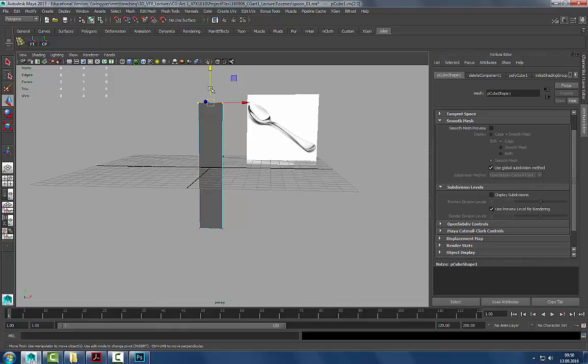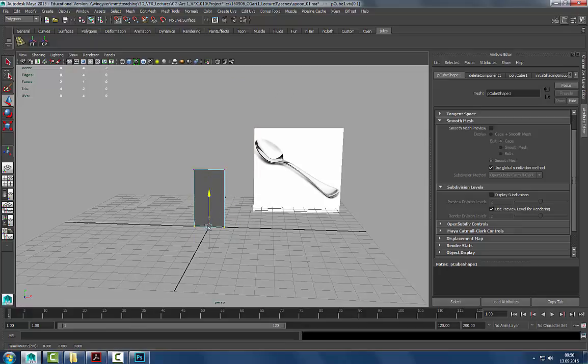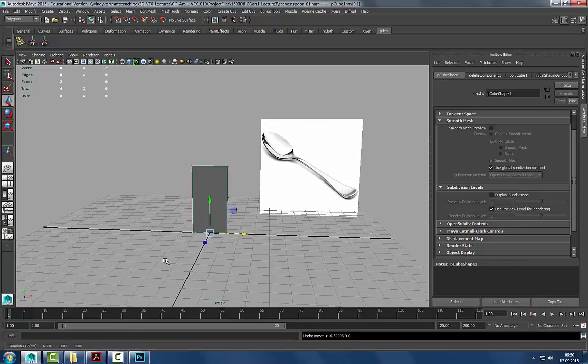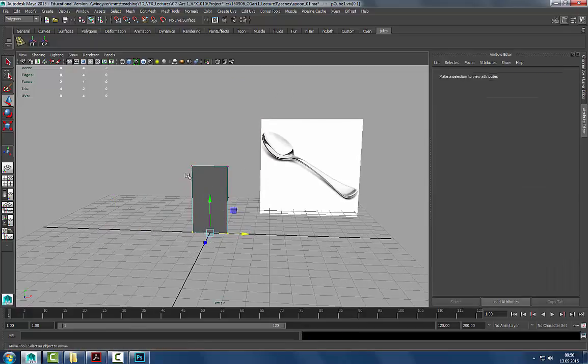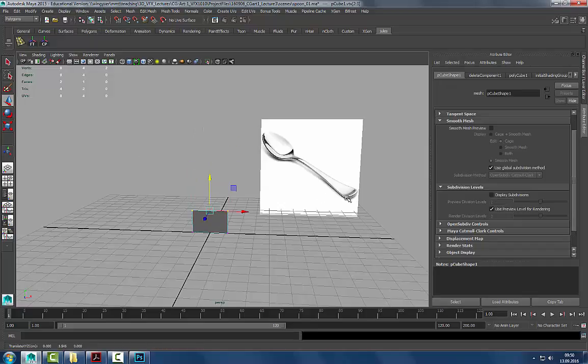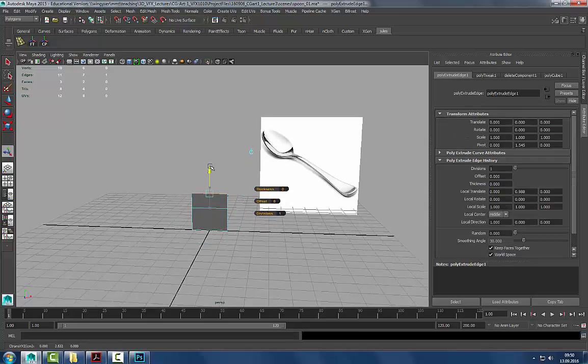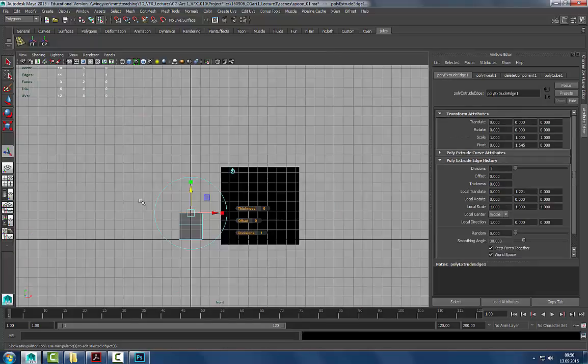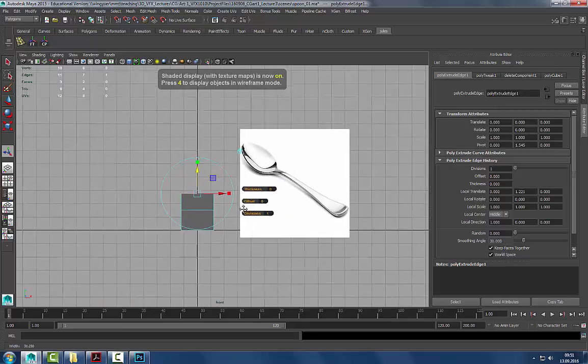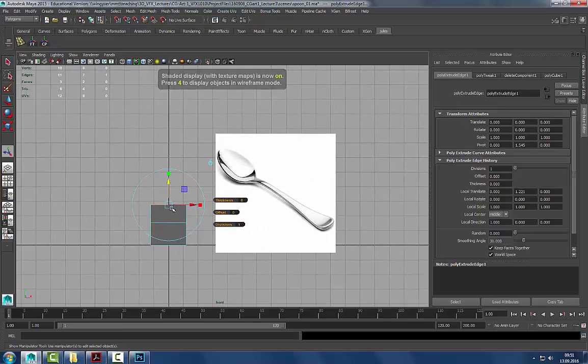Okay, so let's just get started. I'm going to grab these verts and just start modeling. Literally just roughing out the shape that I see. So I'm going to press Control E. Let's go to the front view. Here I can hold Control and scale pressing this axis, or I could grab this axis.